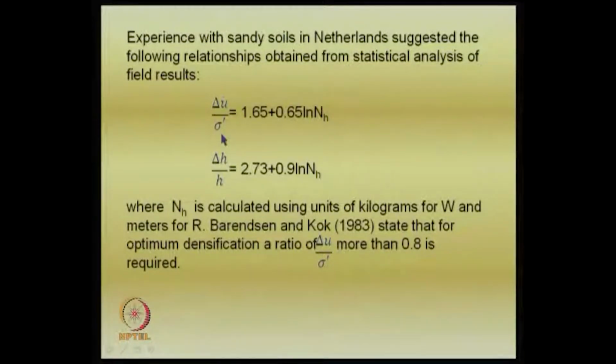If you are looking at the pore pressure ratio, what it means is that you are looking at a pore pressure ratio of 0.8 divided by the initial effective stress. So one can really design this NH, and we also have in the previous equation some term related to the radius. You can combine some of these numbers and get some estimate, but the important thing is that a lot of analysis methods are available. One should use these empirical equations with caution. One can do a systematic study on this and then come out with actual